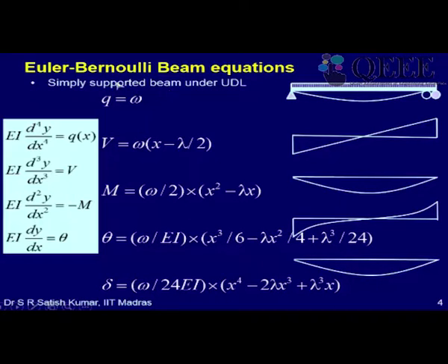So this set of equations helps you solve this beam very easily, and you get to know everything about the shear force diagram, the bending moment diagram, the slope diagram, and the deflection diagram. All these deflection diagrams are also called the elastic curve because it is the shape that the beam will assume when it deflects. Now it's very important for us to understand this relationship by also looking only at the figures. So here let's look at this.